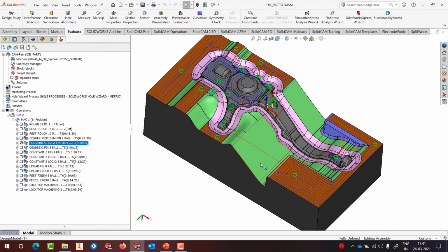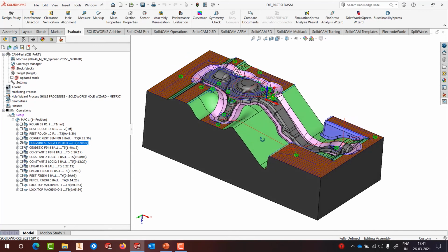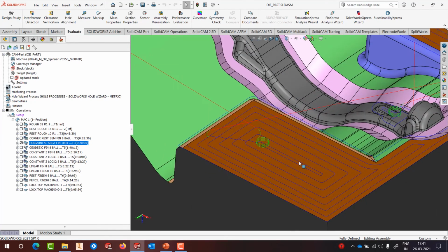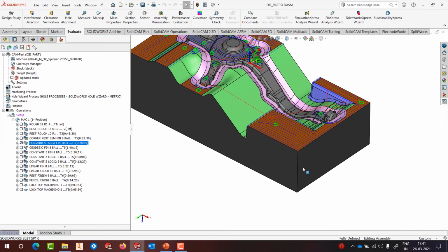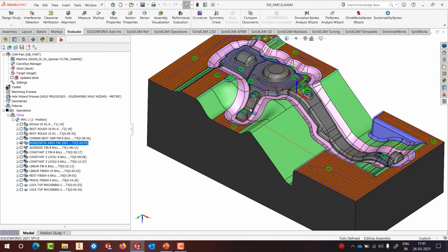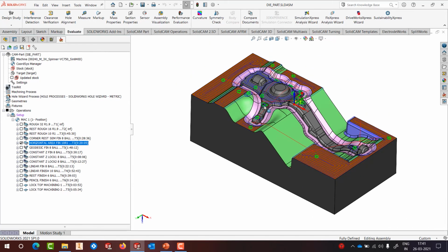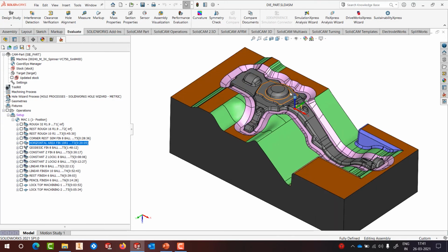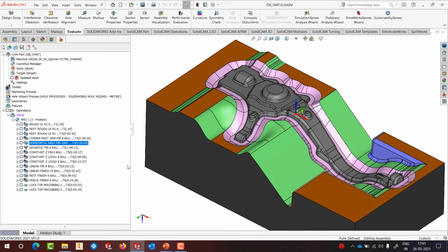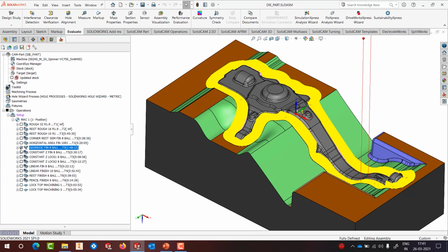This is how the toolpath looks like. It's ramped and it's only detecting and machining regions that are absolutely parallel to the XY plane, which have got absolutely 0-degree slope. And then we use the new generation functionality of geodesic machining to machine some regions which we feel are suitable to geodesic machining.